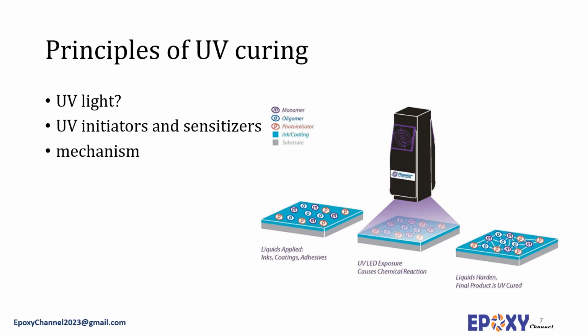It must be noted that the energy of UV radiation with wavelengths of 100 to 280 nanometers is very high, as it is often absorbed by the upper layers, which leads to an incomplete cure in the lower layer of the film. Therefore, UV light of longer wavelengths, for example 315 to 380 nanometers, is preferred for UV curing.